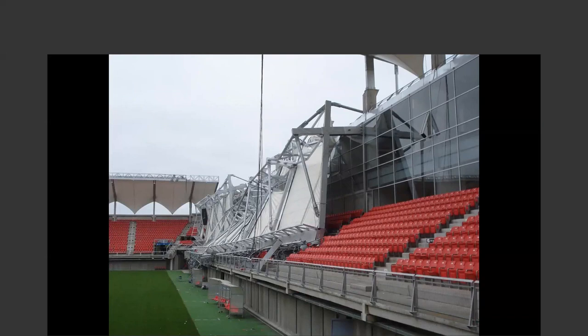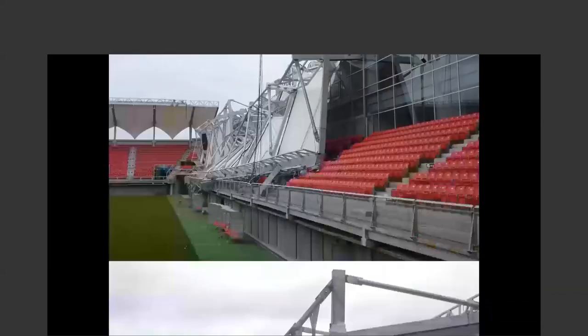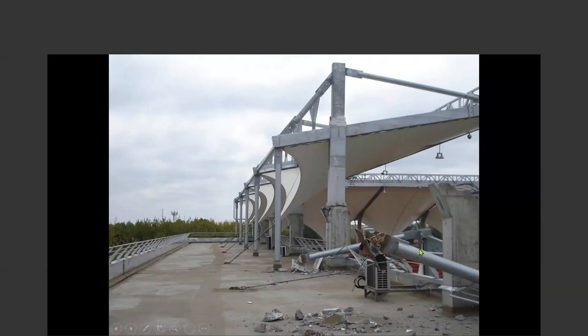This was when we went to Chile after the 2010 earthquake, huge earthquake. This was somewhere between Santiago, the capital, and the Pacific coast. The epicentral area, Concepcion, was the town. This was somewhere in between, a small place. We saw a stadium, and the seats had this kind of a fabric roof, if you like, and in this part of the stadium the roof had come down, and when we tried to look for a reason, the roof was supported by those steel columns or whatever you want to call them, which were mounted on concrete pedestals. Okay, and here you can see signs of failure.